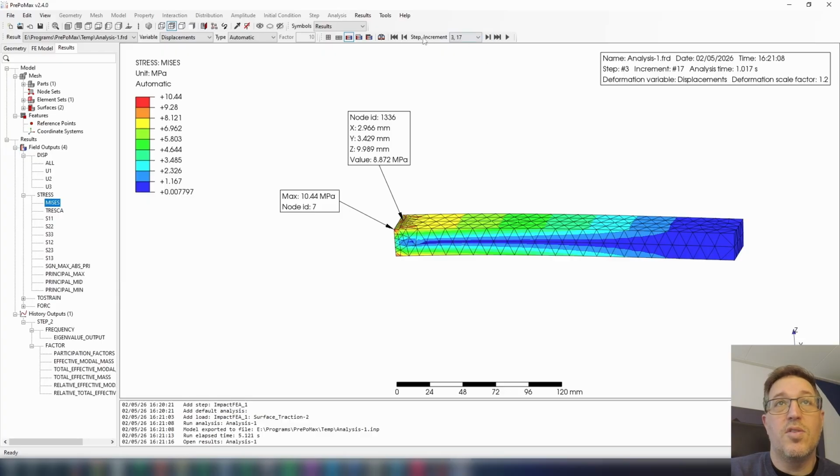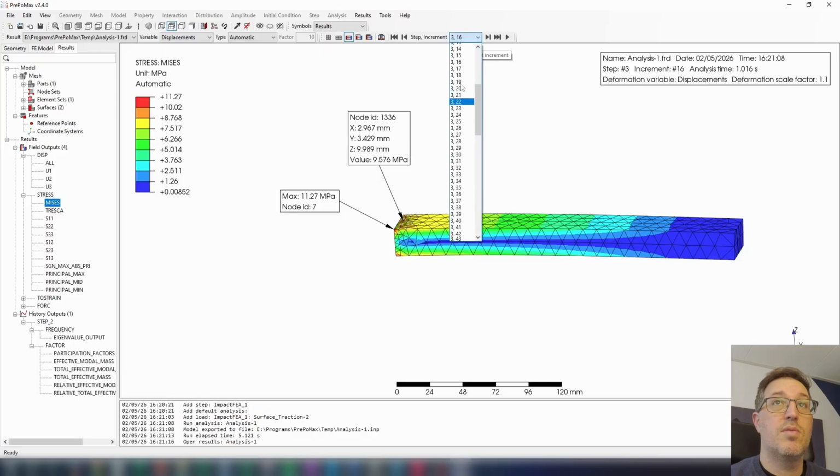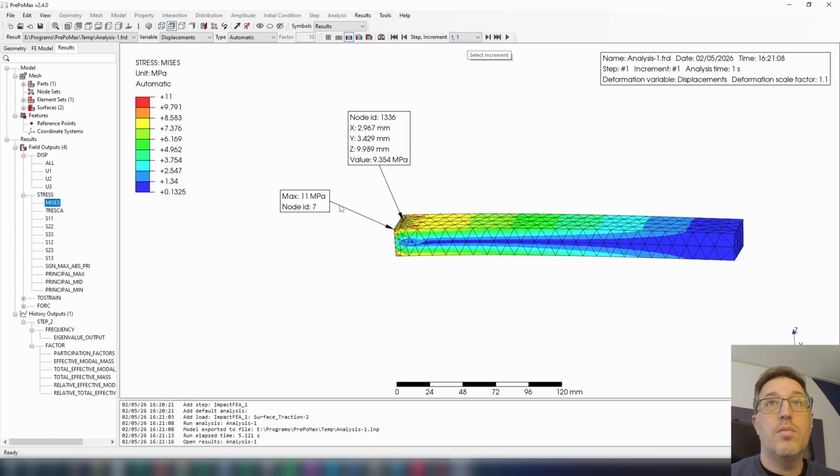So this is actually a good result. I'm not scared that this is different because at the level of 11.2 to 11 megapascals, we're not looking for the most accurate results, but we're looking for a way for us to estimate whether we need to make changes or not to the design, because we're on a design phase. This is not a final analysis, so we can use this as a tool. But we can see here it's pretty much equivalent to the results of the static analysis, which is here. So that's interesting.